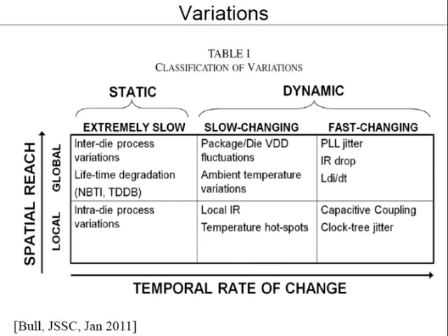When I say threshold voltage, which threshold voltage am I talking about? Every transistor has its own threshold voltage. So if you take the same transistor in another chip, because you are taking the design and stamping it, the same thing you are stamping, the same transistor you look at in another chip will have a threshold voltage a little different. So chip to chip there is variation.